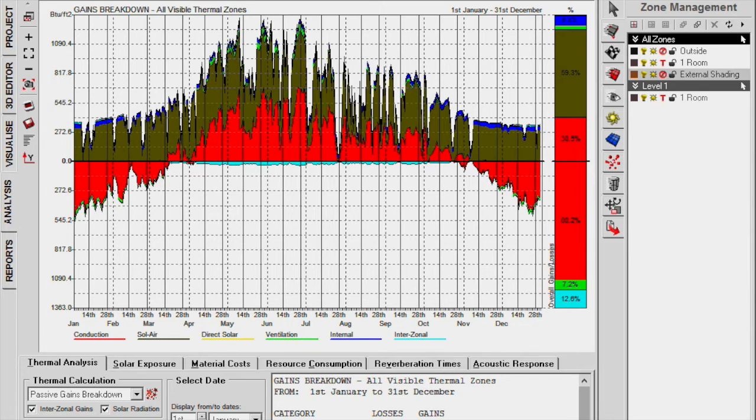So as we look at the amount of heat that's flowing in or out of the building relative to the outside temperature, changing the thermal properties of the wall, either the U or the R, is going to change the amount of conductance. And that's the direct effect. So when we think about it being 60 outside and we want it to be 80 inside, what's resisting the heat flowing out is that resistance of the conductance. Okay, so that's the first important factor. If we wanted to change that, we'd be changing the R value or the U value of the wall.